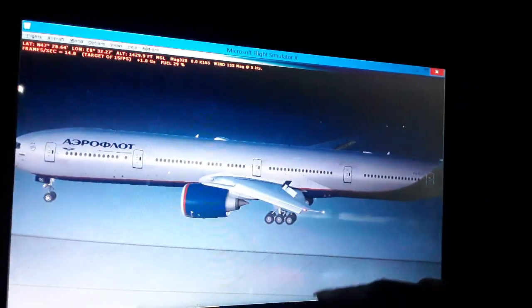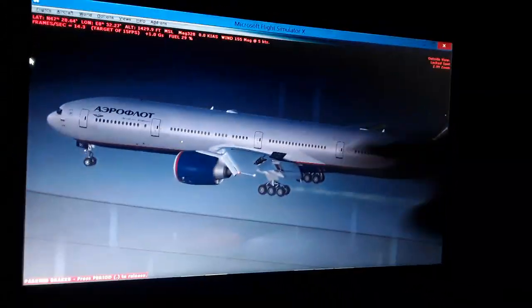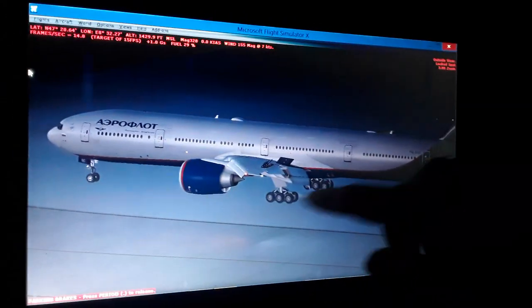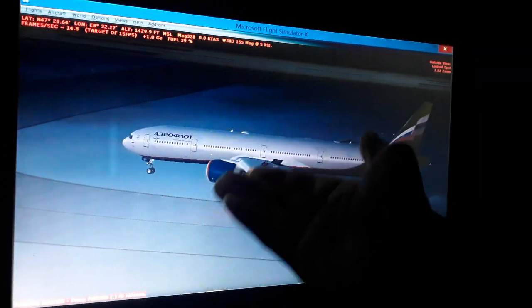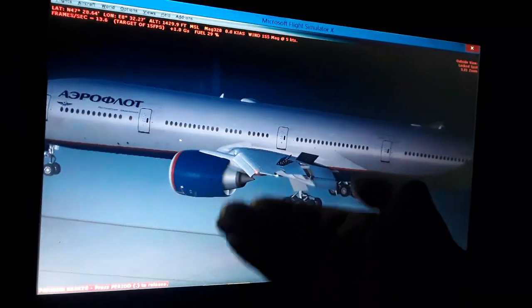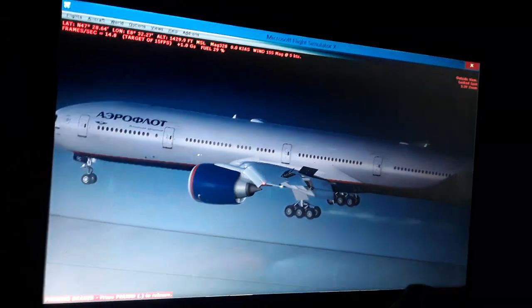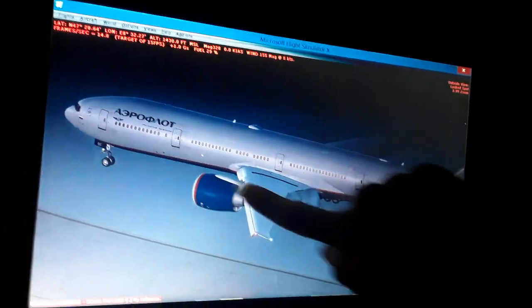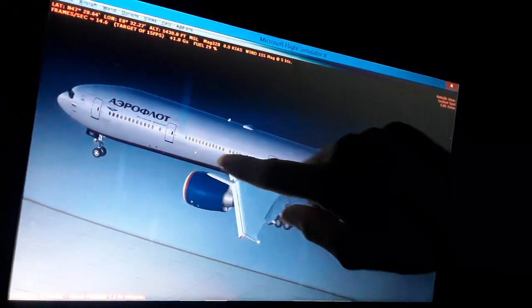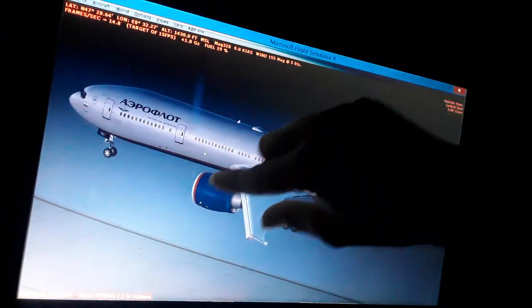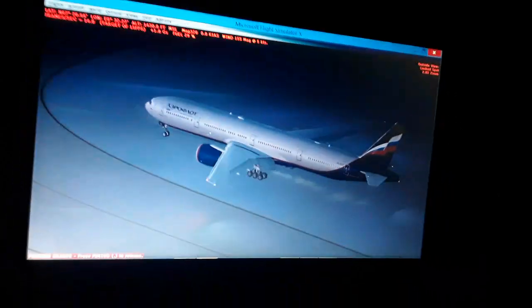So we have also the wings here of the aircraft. You can see the bottom surface of the wings is more flat here. So as the aircraft accelerates for takeoff, there is a higher air pressure below the wings, which pushes the aircraft wings up into the air using the Bernoulli principle. Also, the top surface of the wings has a higher curvature, so the airflow of the air mass is moving much faster above the wings. So there is a lower air pressure above the wings, which sucks the aircraft up into the air.